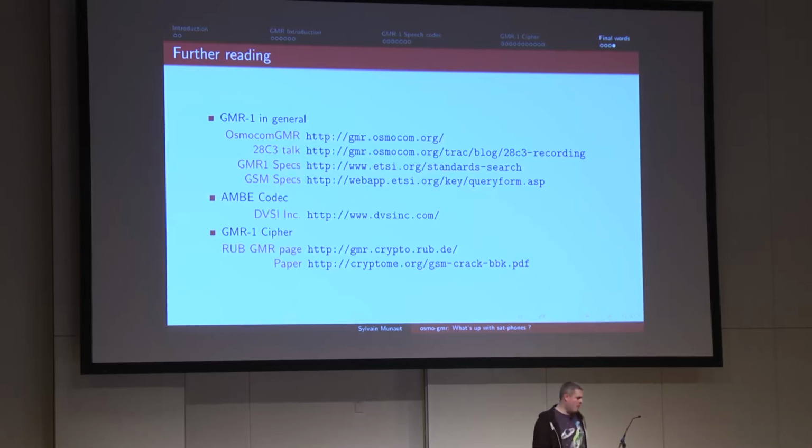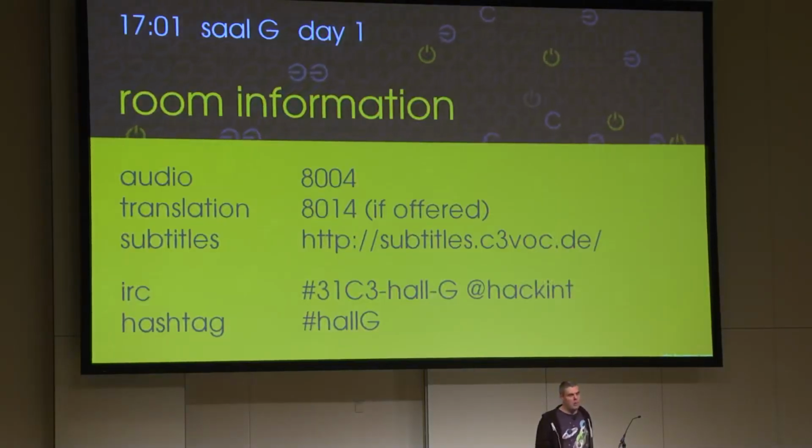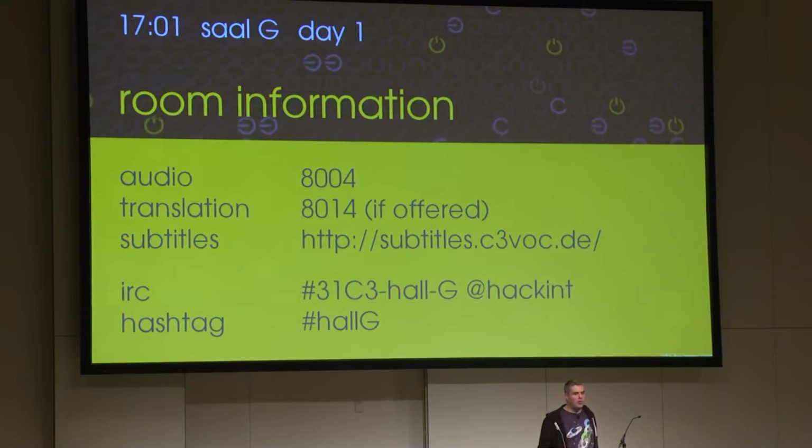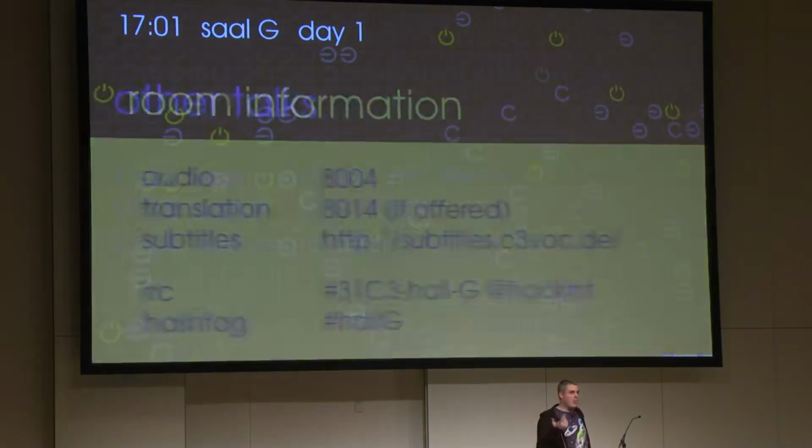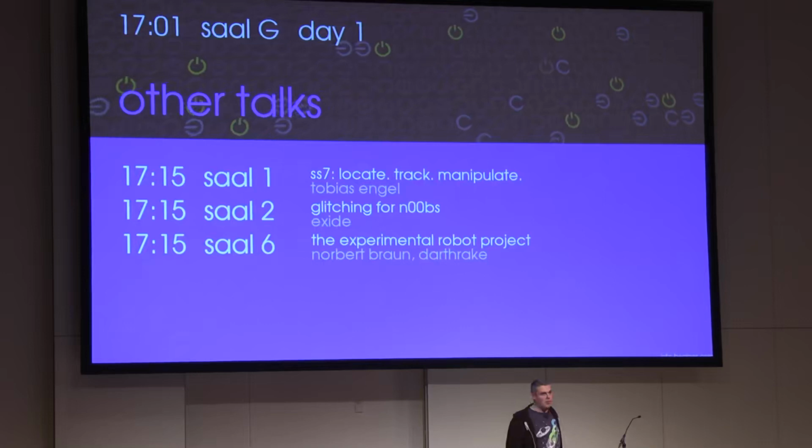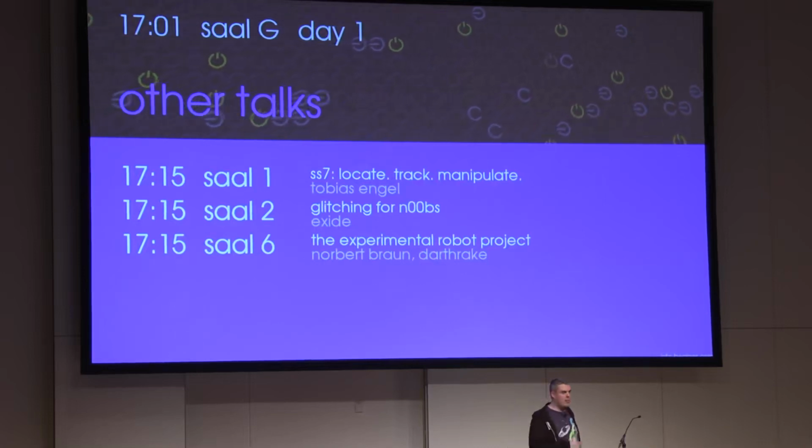Not really. I mean, it'd be interesting to try to start a net, because there is nothing that says that you have to be on a satellite. You could technically start a base station on Earth using that protocol, and it would work. And the phones have much more power than a GSM phone. But other than that, you could build an IMSI catcher for satellite phones if you wanted to. And you would definitely beat the signal strength of the satellite with your own setup.